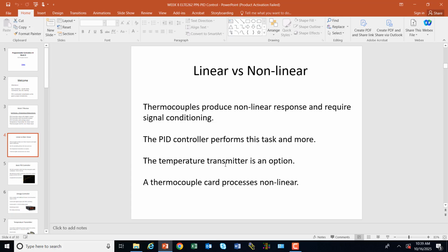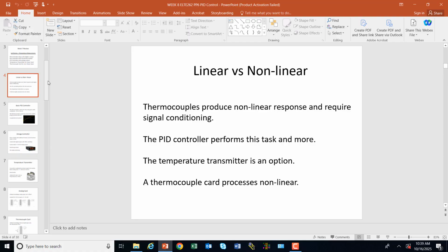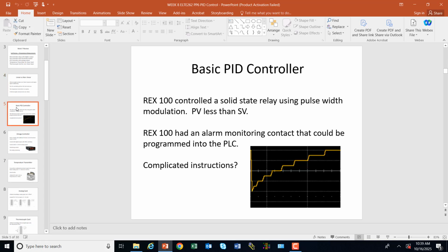But with the nonlinear process, the thermocouple card was a little bit trickier because we didn't have any cold junction compensation on there, so our offsets seemed significant. You'd think, well, what's the difference between room temperature and 0 degrees? Can we use that as an offset? Yeah, kind of, but those were giving us some weird numbers, and we'll talk about it.